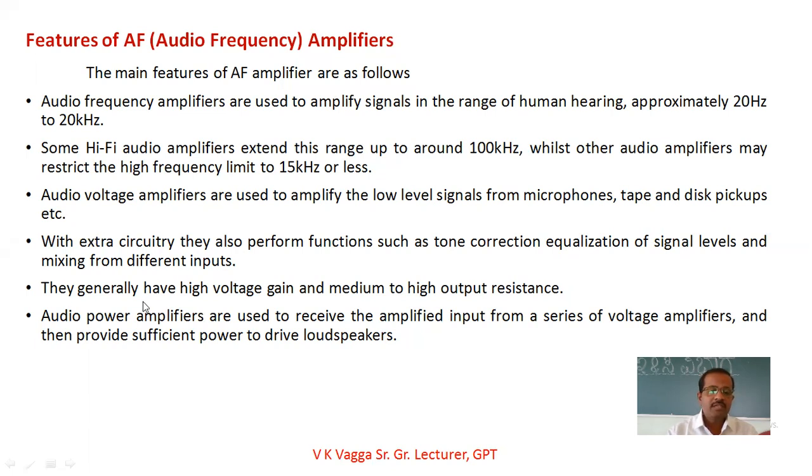They generally have a high voltage gain and a medium to high output resistance here. And audio power amplifiers are used to receive the amplified input from the series of the voltage amplifier, and then provide sufficient power to drive the loudspeaker.